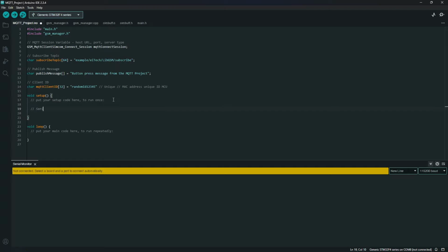The next thing that we want to do is come into our setup, and we're going to do our serial setup first. So for the serial setup, we're going to do serial.begin. This is going to be your serial debug output. So effectively anything that comes out of the serial monitor is going to be linked to serial. And then this is optional code, but I like to include it, especially when we want to see anything that is output on the serial monitor immediately at boot up. Otherwise, the code will run so fast that you'll miss the first outputs before this actual serial setup is complete.